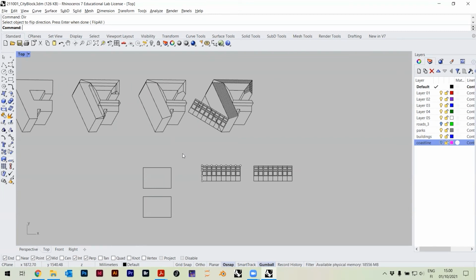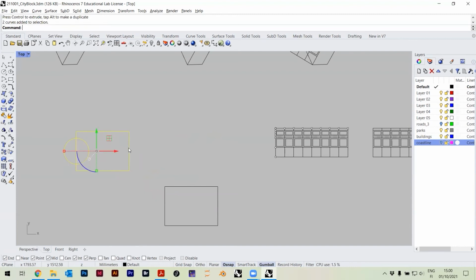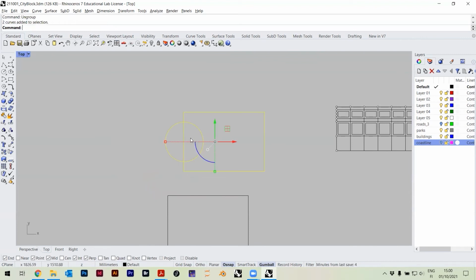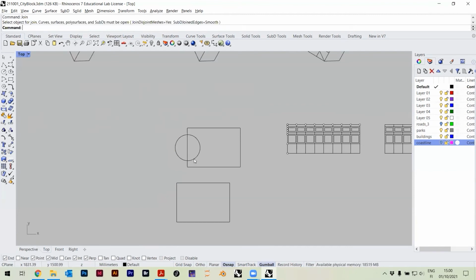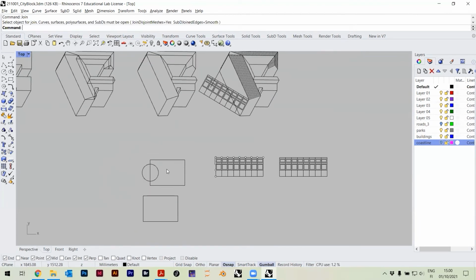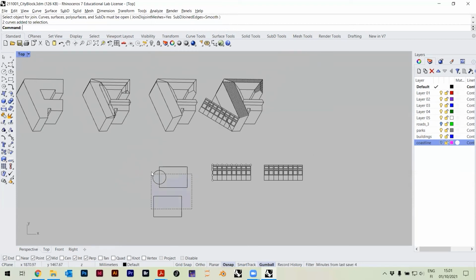Also, you can always group elements together. For example, I can have a circle, and I have this rectangle. I can always group them together. So now this is a group, and I can move it around, same as before. But I can ungroup, but I cannot join these two. There's no way to join. If I say join, it will say these cannot be joined because it's not really clear how they should join. I can join lines that have endpoints at the same place, but these are just two separate objects on top of each other. So I hope that explains a little bit the difference.